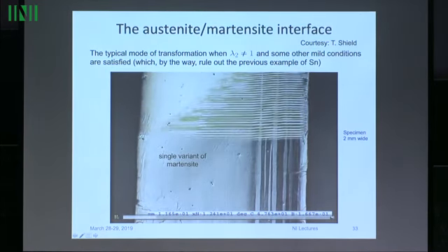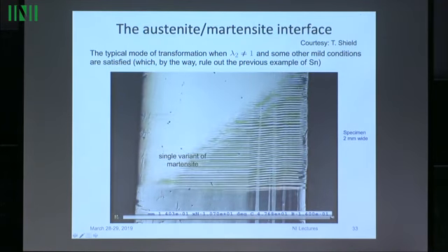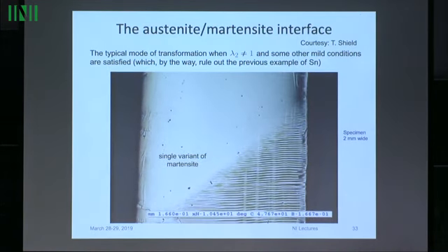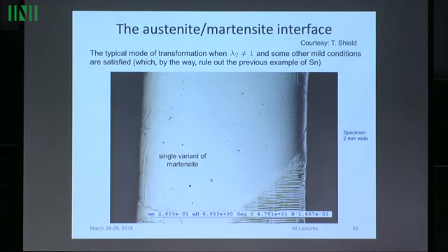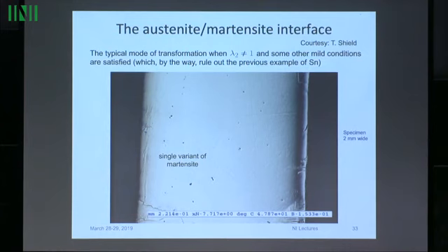Now what's really interesting, you can see the branching, by the way. What's really interesting about this picture is now this is austenite. This was heated up. So we started with a single variant of martensite. So we started in the low temperature phase, and there were some other variants that didn't get detwinned over here. But anyway, most of it was single variant martensite.